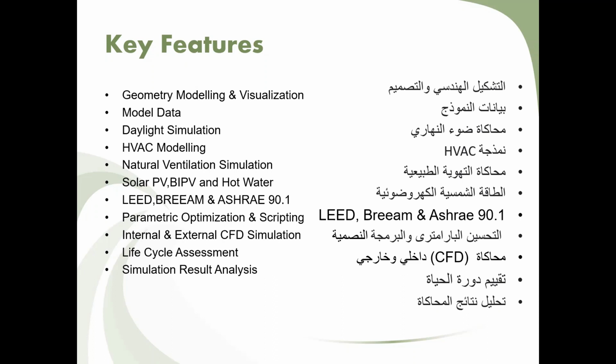And apart from this, we have separate dedicated modules for compliance with ASHRAE 90.1 and LEED for different credits for energy and daylighting. Then for researchers, or for those who want to optimize their design, they have parametric optimization and scripting options available as well. Then we can perform even CFD simulation within this, and we have LCA integration and simulation result analysis, which we can do within the software, and an external freeware software is available as well for detailed post processing. Okay.